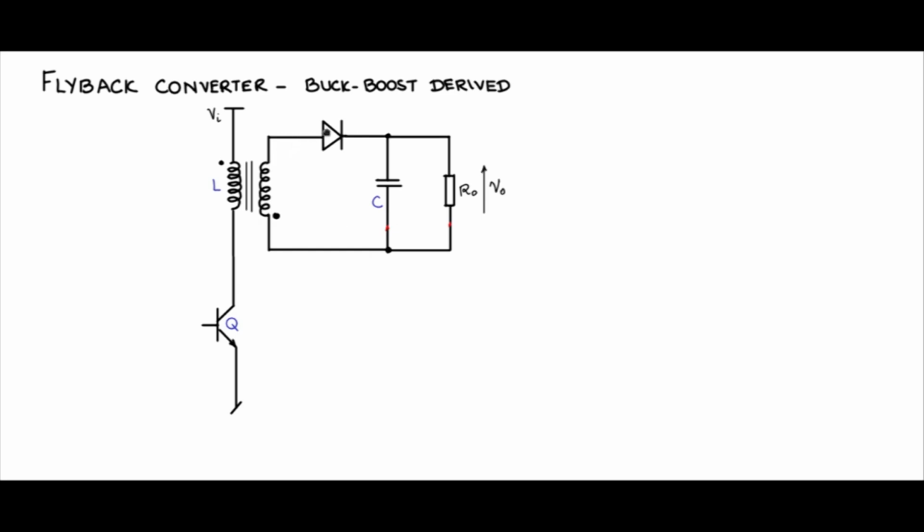And if you reverse the diode, the capacitor will get charged in this direction, plus and minus, and we will have, as measured in this fashion, a positive voltage. So just to make it more pleasing, we have reversed the position of the diodes and the dot polarities without loss of generality. The operation still remains the same.